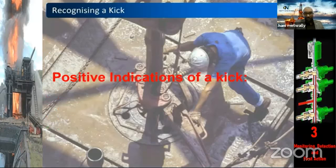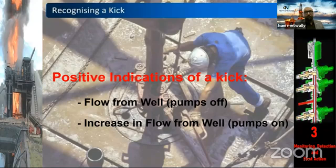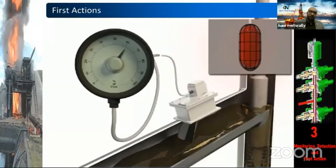So we can make a summary. What are the positive indicators of a kick? We have a flow from the well with the pump off. So shut down the pump and we still have a flow. Or during pumping, the flow from the well increases, and the level in the tank, the pit volume, has a gain. All of these are warning signs and indicators.